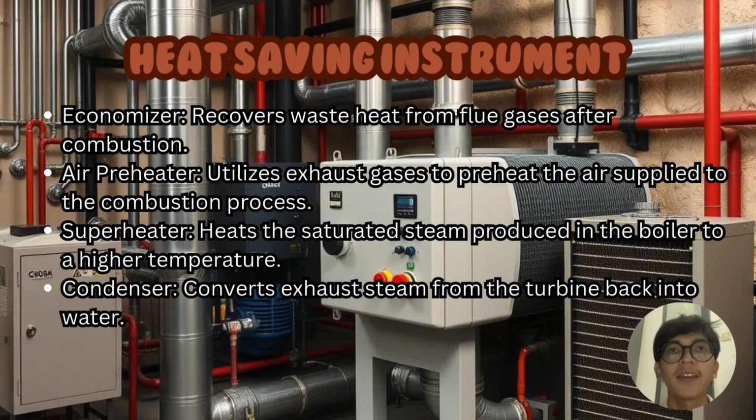01EKM22F1109. And now I will talk about heat saving instrument. The first one is economizer. The purpose of economizer is to recover waste heat from flue gases after combustion. The contribution for economizer is preheats the feed water before it enters the boilers. By using waste heat, it reduces fuel consumption and enhances boiler efficiency. It typically improves overall plant efficiency by 1 to 2%.